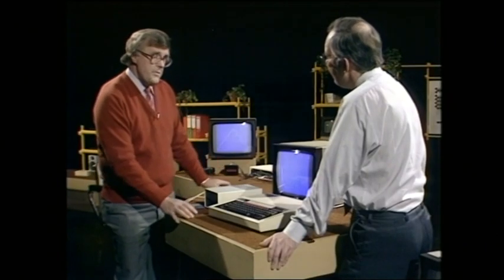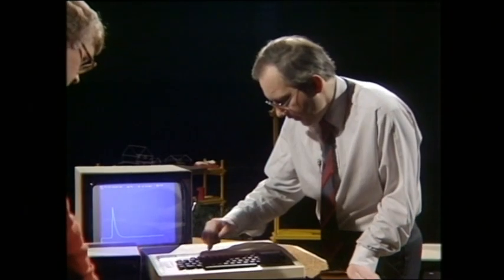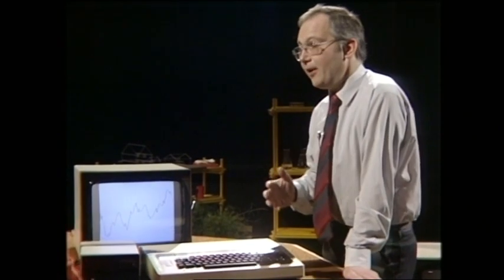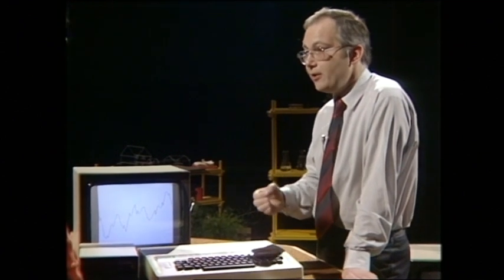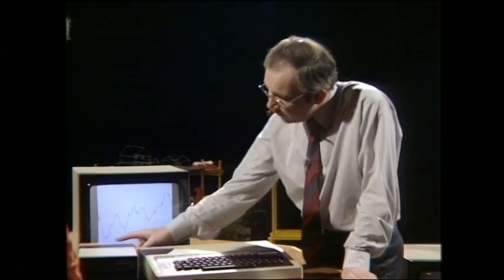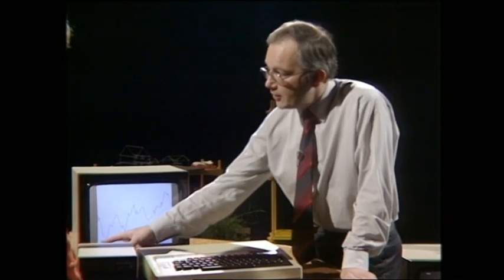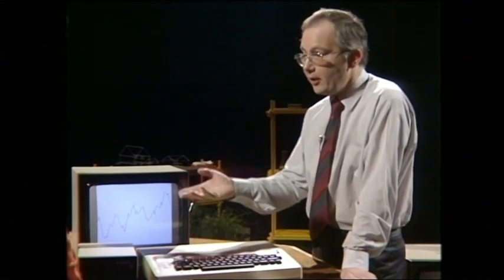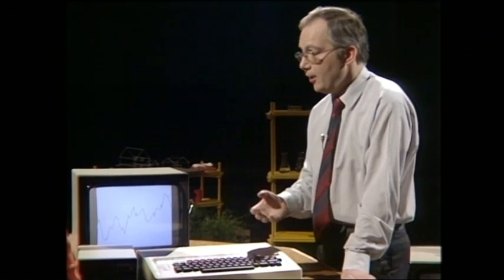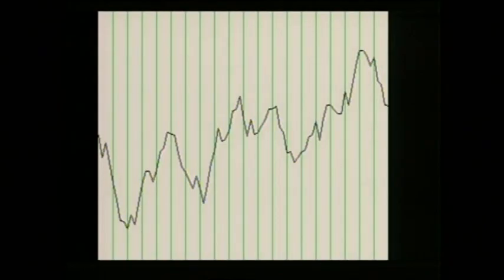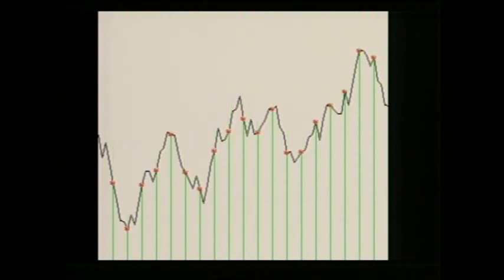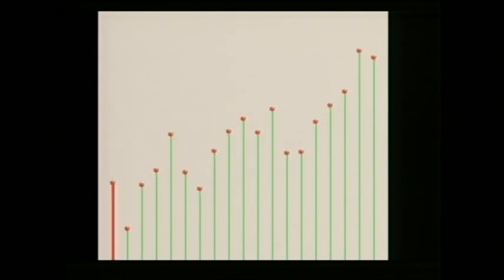How do they actually work inside the machine? OK, well, I've got a program, needless to say, to illustrate this. The fundamental thing about analog quantities is that they vary. They don't just have ons and offs, they vary. And you can see the graph here, which represents the voltage of some signal against the time. And as you said, the microphone and the pressure pad are both producing voltages. Now, the computer samples those voltages at regular intervals, maybe every 50th of a second. And it then decides what the height of the signal is at those moments in time. And it reads those numbers in to the computer. That's an analog to digital conversion. We fed an analog signal in, and we've got a digital result to deal with.